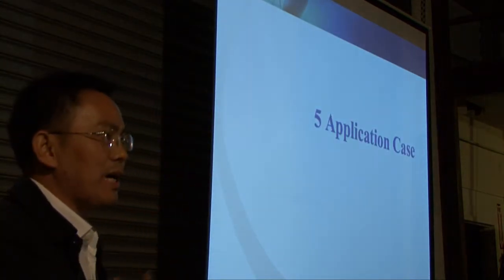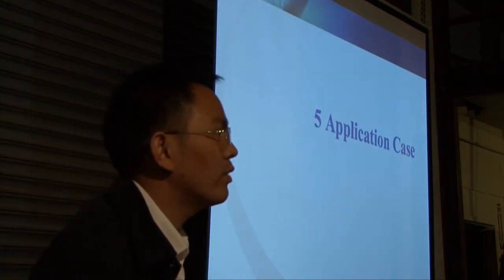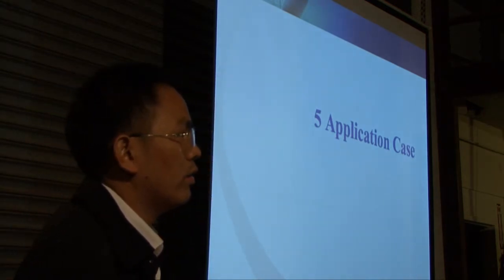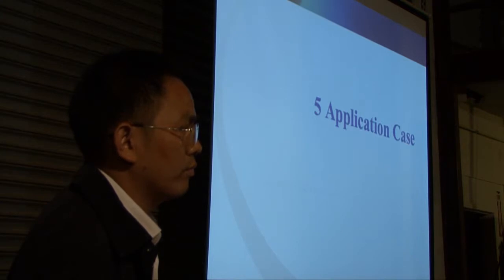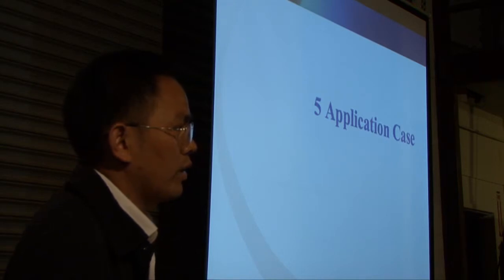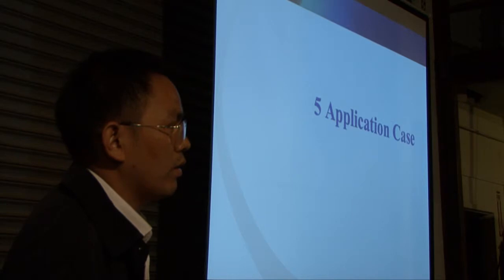Okay, I will do some application cases. Sorry, yes. Before you go there, I'm curious why for the CO you decided to use an NDIR. It seems you could use a very basic electrochemical cell, because you can solve the cross-sensitivity between CO and the H2 and CH4 by your thermal conductivity for the hydrogen and your NDIR for the CH4. It doesn't seem you would need the accuracy of the NDIR on the CO. We think you could mathematically solve it with a much dirtier filter or cross-sensitive filter on the CO.